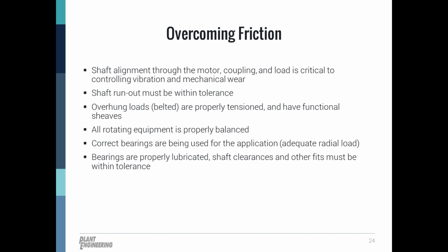Just to reiterate, we did talk a lot about bearings. The bearings are the number one cause of motor failure, so it's very important to follow your preventative maintenance techniques with your bearings: periodic lubrication, vibration analysis. Even when you're greasing the bearings, you've got to verify you're using the right grease. These days, I think Polyrex EM is the most commonly recommended grease type. And also, if you need to measure that grease, measure it. Find some way to weigh the grease before you put it in. The bearings should be maintained based on run hours, and product literature from the bearing manufacturer should give specific details on the lubrication type, the interval, and the amount to add.